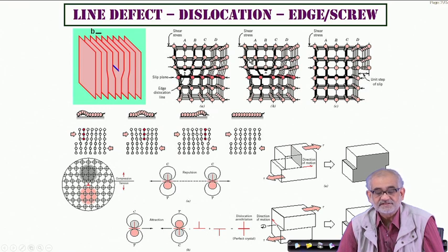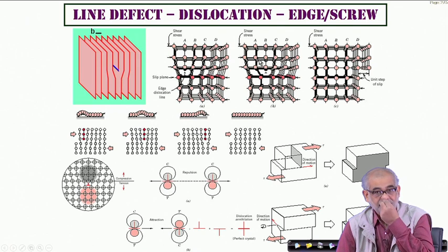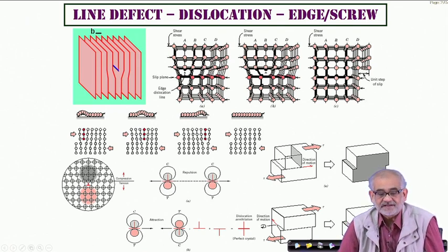So that means there is a closure failure, and the closure failure, dimension-wise and direction-wise, defines a particular characteristic feature called Burgers vector, which defines exactly the existence and the dimension of a so-called edge dislocation. Whenever you have such an extra half plane introduced inside the crystal, this blue line here defines the end of this extra half plane.